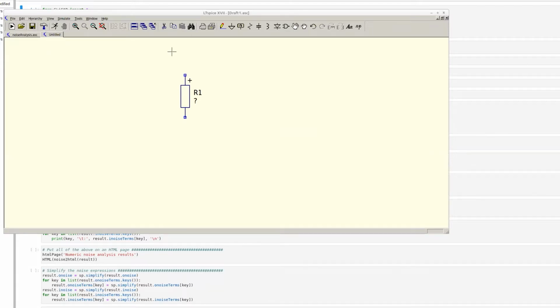If you want to have the noise of the resistor included, because in symbolic analysis you always want the simplest model possible, otherwise your symbolic calculator cannot do anything, or cannot solve it, or your expressions will be so complex that they are not meaningful at all. You cannot draw any design conclusion from it. So very important for the application of SLiCAP is that we make simple models that only model the thing that we want to investigate at that point.